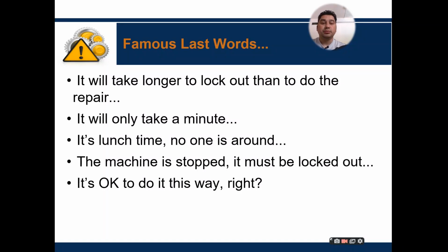Now, famous last words. These are the words people usually use to avoid the lockout tagout process. They will say it will take longer to lock out than to do the repair. I can do the repair within a minute. Why do I need to spend so much time on the lockout process? It will only take a minute to repair a machine. Or, it's lunchtime, so no one is around, so they will not use it. The machine is stopped, so it must be locked out. The assumption: it's okay to do it this way, right? They don't understand the importance of the lockout tagout process.